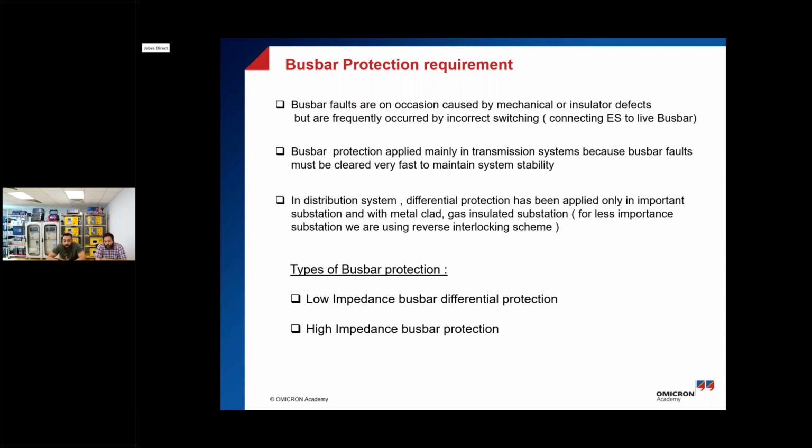Yes. And actually this is the point: when you are talking about the short circuit level, or you are saying that the short circuit level capacity in this substation is, for example, 40 kilo amp, this is the withstand current for the busbar protection, not for the equipment, because the highest fault in the substation will be mainly on the busbar.